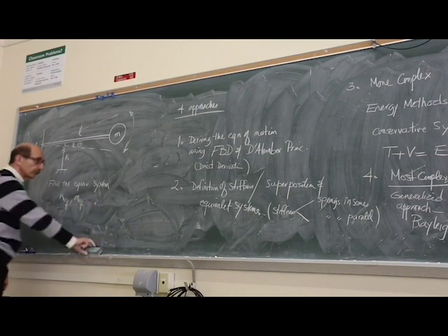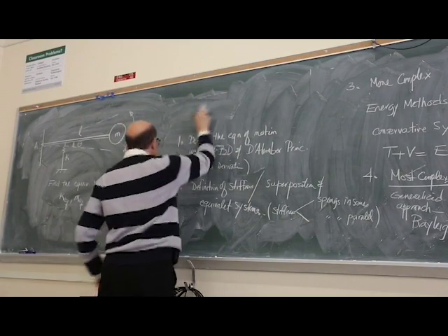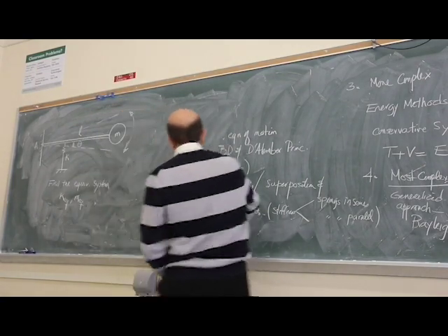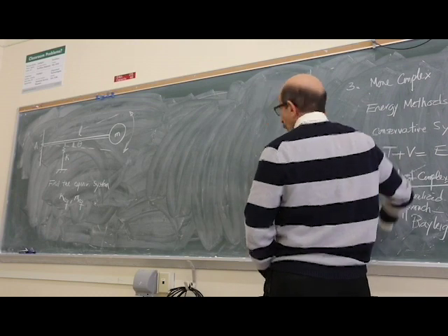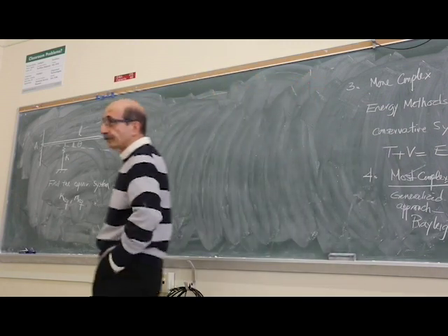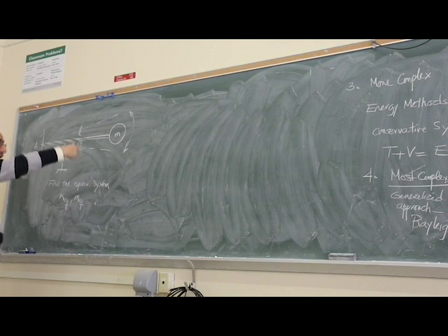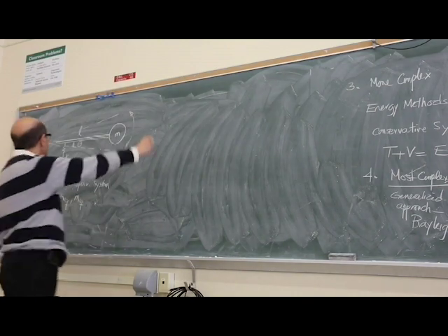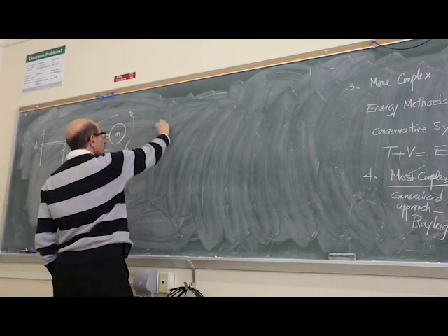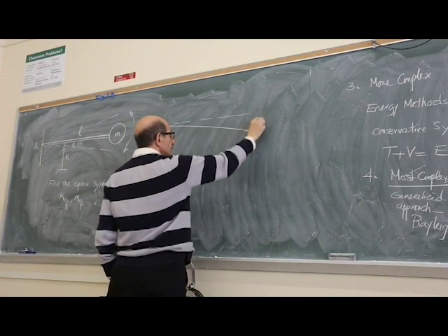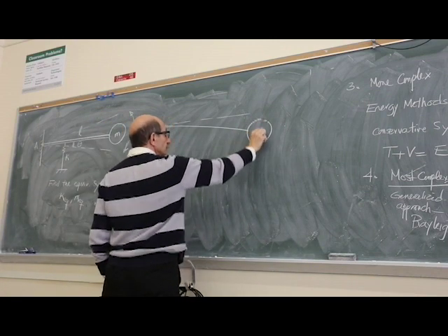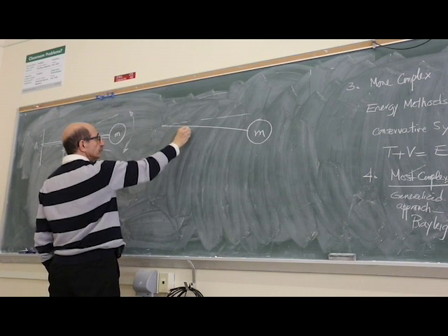What we mean by equivalent system is to find K and M equivalent in this system. Okay? So approach 1 again is deriving the equation of motion using the direct approach for a single degree of freedom system, by setting up the free body diagram of the system. As this thing is going through deformation, it is going to deform like this, right?